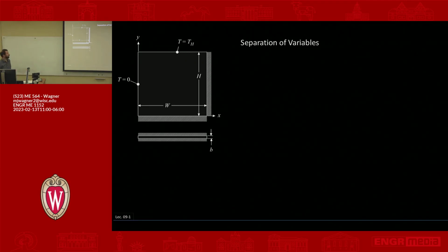Let's say we go through our Biot number calculation and it's 0.2 or 0.5 or something. Now we have to do something like this. This is a more difficult solution. It's not hard to do, it just is more work. But there are different techniques that we're going to go through to solve these. The separation of variables idea is probably best communicated through an example because there are 5 or 6 steps we have to go through. So let's go into this particular example, and I'll talk through the steps as we go, and we can understand it that way.